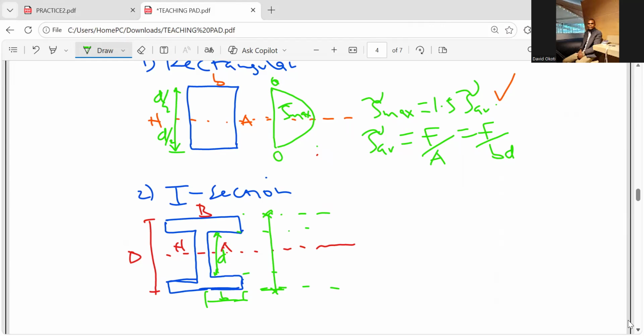Now from there, you go to this point here, the junction between the top flange and the web. There you will plot one stress in the flange part. After that, still at the same point, you plot stress in the web part. Because the web is narrow, the value of stress will be higher. That is why you find that at the same line through the junction, we are plotting 2 points. The first point is due to flange and the second point is due to web.